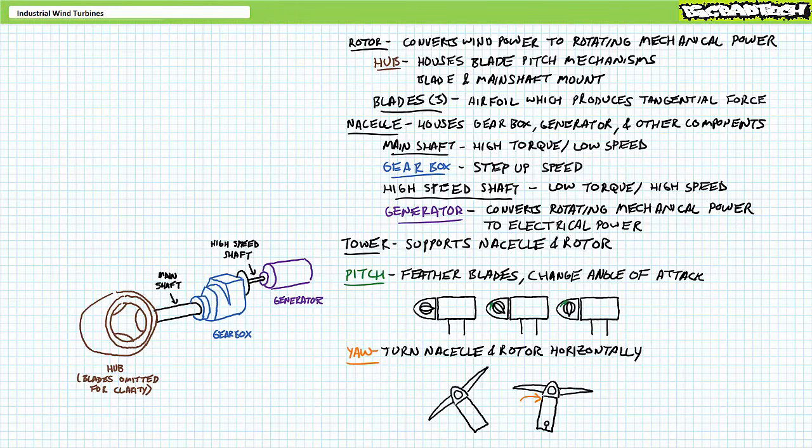Today we'll take a closer look at the elements comprising the rotor, including the blades, hub, 2 types of pitching mechanisms, electrical and hydraulic, those elements inside the nacelle including the drivetrain consisting of the main shaft, gearbox, high-speed shaft, coupling and parking brake, the generator, controller, as well as the tower and other accessory elements, including power distribution, power conditioning, and performance monitoring systems. Later lectures will take a closer look at some of these subsystems in greater detail.